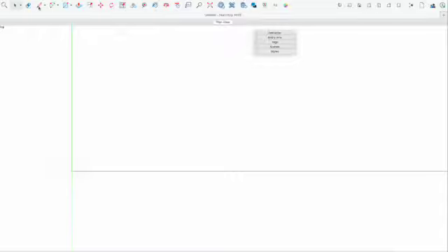Okay, let's click on the line tool that looks like a pencil. If I click on the model area, I can draw a straight line in any direction. When I want to change direction, I click down to end that line segment. You will notice that there are little dots that appear at the ends of the lines when I get near them. That allows you to connect your line in a specific location, like at the end or in the middle. If you click back to your original point, it will close the shape. That will become important later when we're creating faces.